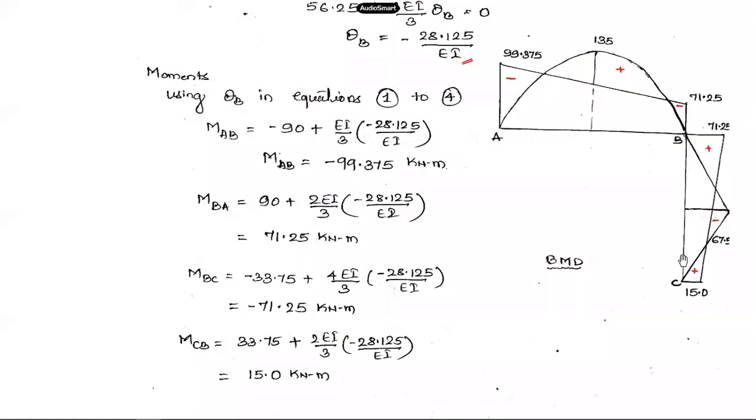Now coming to the vertical member, this column BC. You have done this for beams also in the same way. Now taking this column BC, at B, I'll take this moment. What is the direction of moment? Anti-clockwise. When you apply an anti-clockwise moment at this joint, it is trying to bend this member BC outwards, something like this, outwards or towards right. So that's why this ordinate I have taken outwards or towards right.